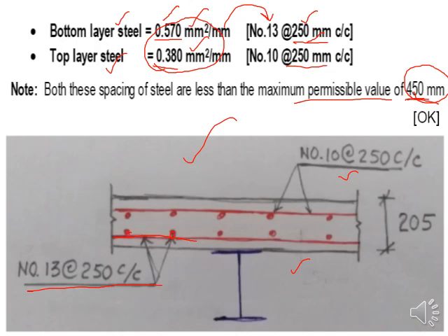So this is the cross section. In the cross section, this is the laterally placed steel and these are the longitudinally placed steel. This is one stringer, one girder that has been shown, and on both of the sides, anywhere in between, you have the continuity sign, just to show the steel more prominently within the bridge deck slab.